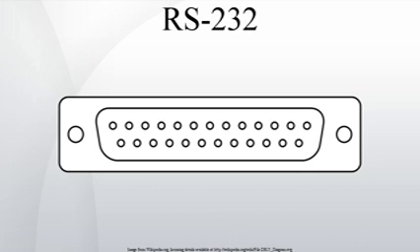In telecommunications, RS-232 is the traditional name for a series of standards for serial binary single-ended data and control signals connecting between DTE and DCE. It is commonly used in computer serial ports. This standard defines the electrical characteristics and timing of signals, the meaning of signals, and the physical size and pinout of connectors. The current version of the standard is TIA-232-F, Interface Between Data Terminal Equipment and Data Circuit-Terminating Equipment Employing Serial Binary Data Interchange, issued in 1997.